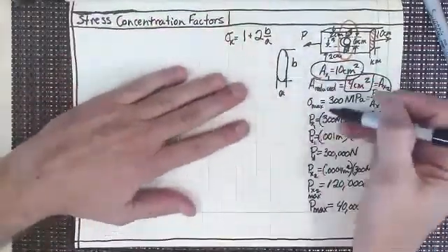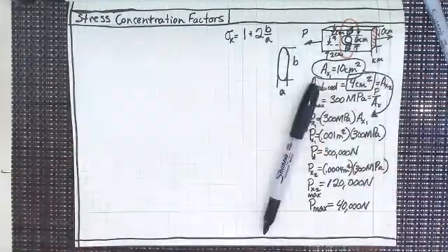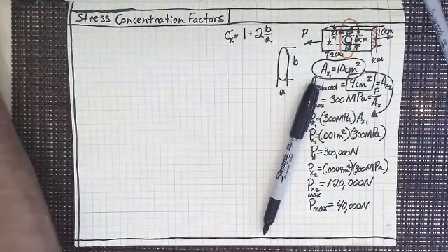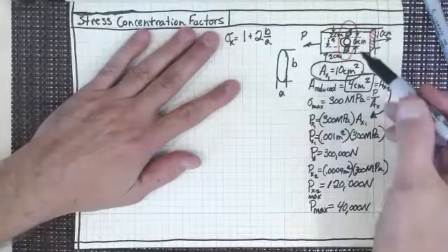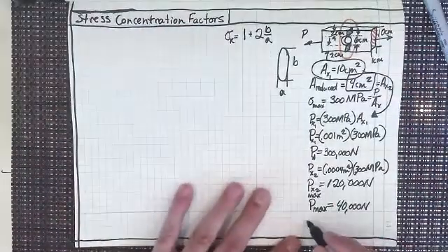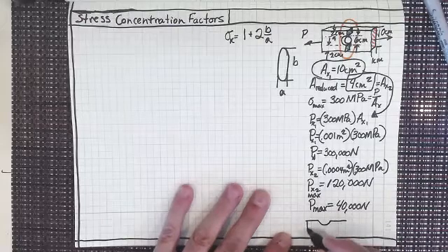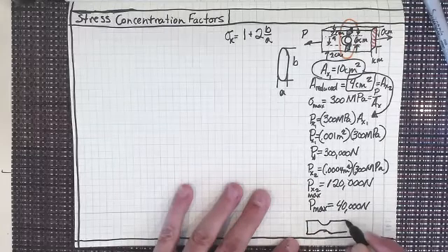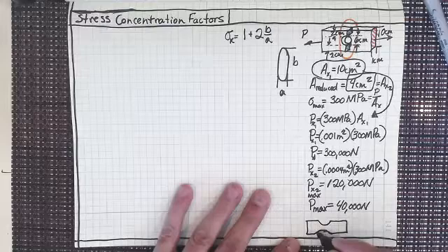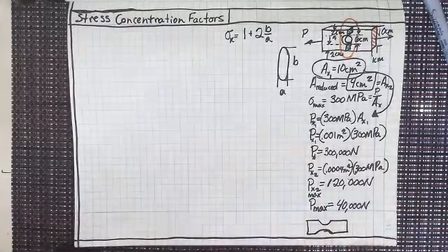We're looking at this, and this is why I want to point out it's not only internal that these, I haven't turned my mic off or anything, have I? No? Let's see. Yeah, okay, good. This is not just internal holes that we've cut out here. For instance, what if I had instead something that was filleted like this? Right, let me just draw this. Isn't that the same as cutting a circle out? I've got to fill it up here, and then I've got to fill it down here, and now I'm working with a reduced cross-sectional area.